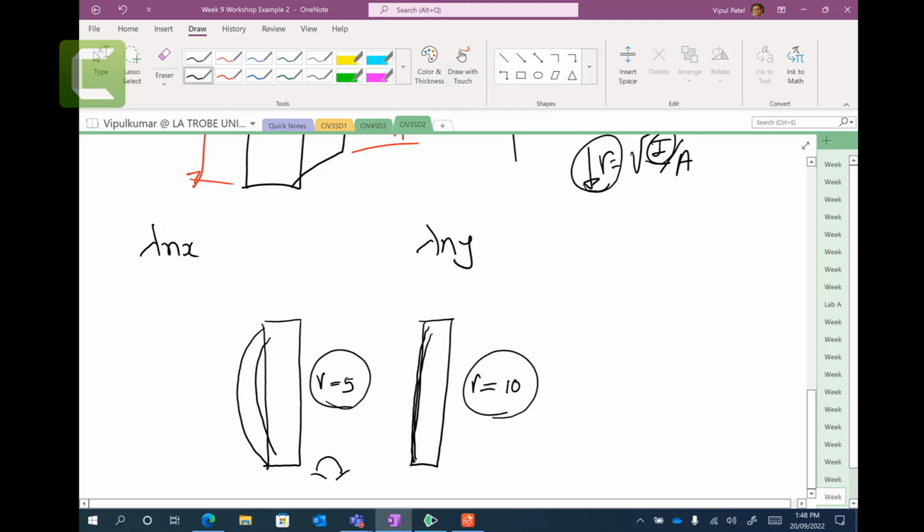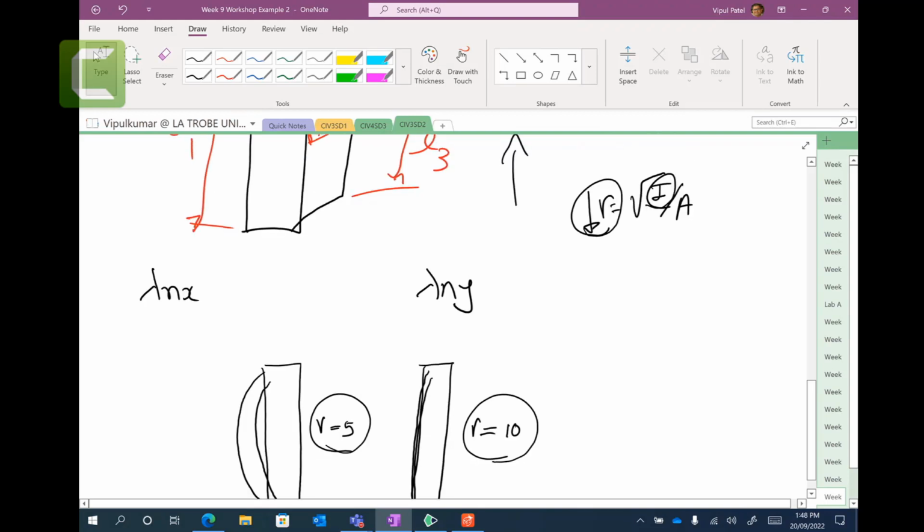With a smaller value you understand that you will get more buckling. But why? You can see there is a relationship between r and moment of inertia. Let's say you have a constant area of the column. But this I is the distribution about that axis of bending. This is the resistance against the moment, against the bending.